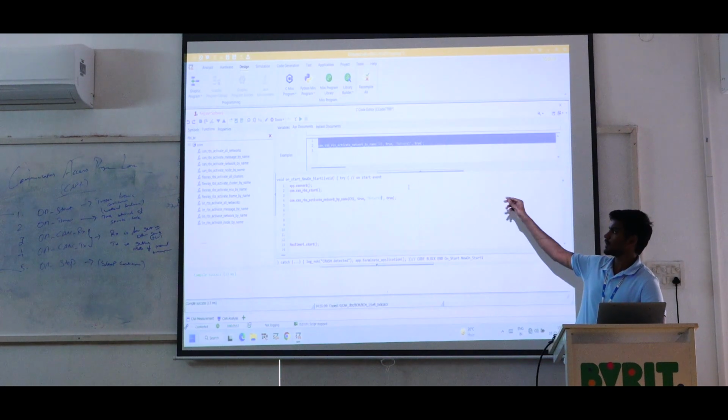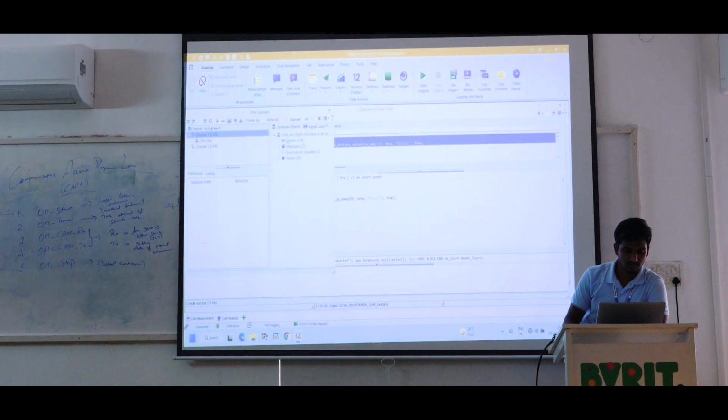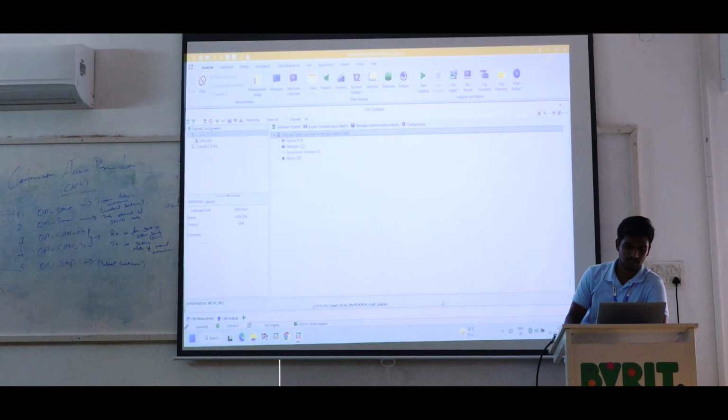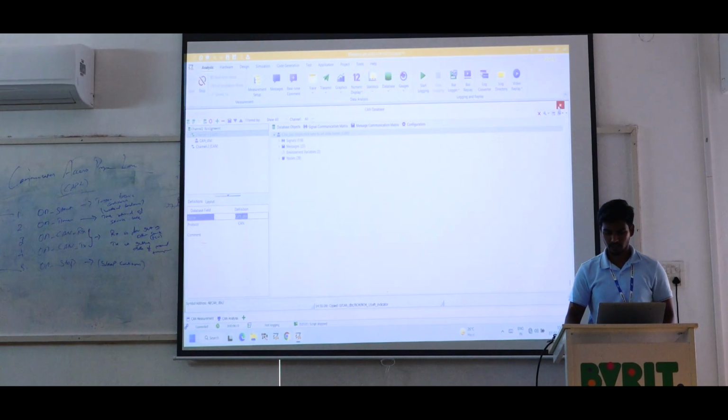So here we need to paste the network name. The network name we have taken from the database. The network name is CAN_DBC. We have to upload the database now. Just click, and we give the name CAN underscore DBC. So just select, copy, and paste it here.